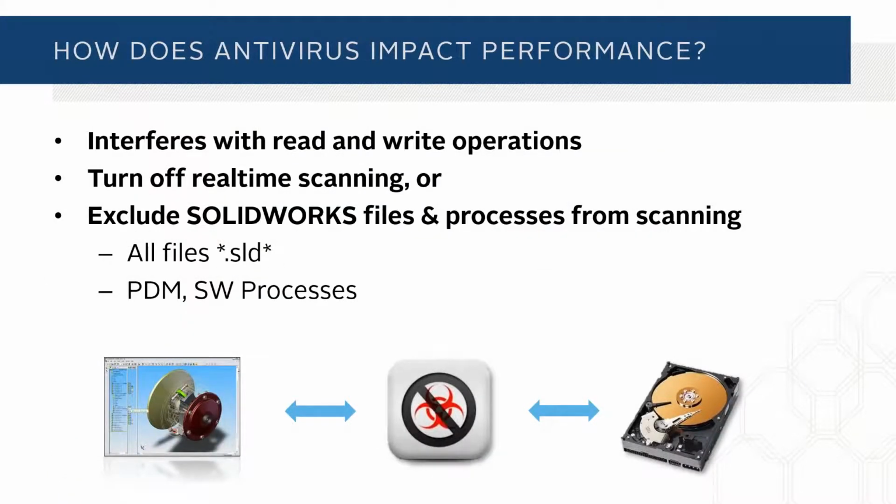Antivirus can also impact your performance as you're using SolidWorks, because pretty much every antivirus software out there today defaults to real-time scanning of every file that you bring from disk to RAM. Now, if you're opening a Microsoft Word document or Excel spreadsheet or a PowerPoint, it's not such a big deal because it's one or maybe a couple of files. But with SolidWorks models, especially assemblies, you might have a 10,000 part assembly that references 6,000 unique documents.